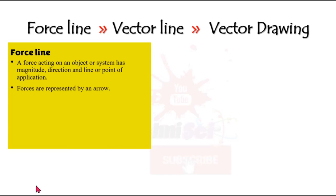They must have an arrow. And why is that? Because a force must have a direction. So that's why an arrow is necessary. The magnitude can be indicated by a label, meaning you indicate the value of the force, or you could use scale drawing, ensuring that the length of the arrow is equivalent to the force itself.